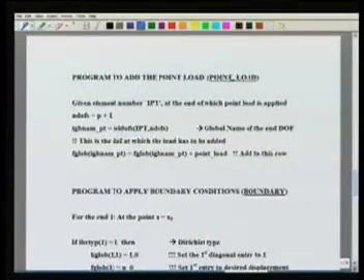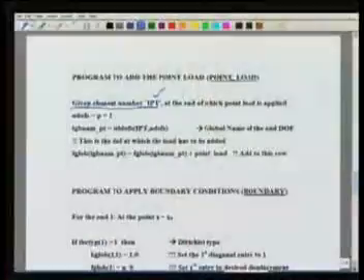First we have to account for the point loads. To account for the point loads, I have a routine called point_load. One can give any name. For this routine, from the meshing routine, I have already extracted the name of the element at the second node of which, or the last node of which, the point load is applied. So I know the name of this element, IPT.